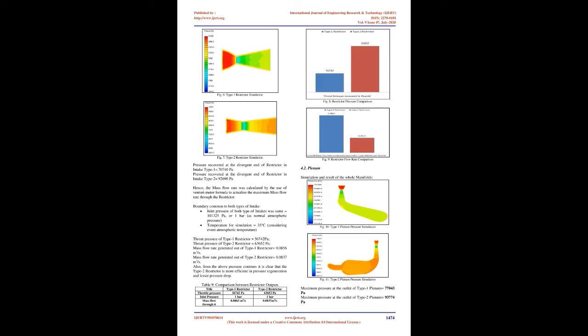1527 mm, which is too big a length to accommodate in the overall packaging of the car, so the fourth order reflective wave is used to get the desired length of the runner to be able to accommodate in the car, which comes to be 381.77 mm. Hence, the manufacturable length is 381.77 - P1 - P2, equals 381.77 - 90 - 80, equals 211.77 mm. This way the exact runner length was found for the max torque at that tuned RPM.